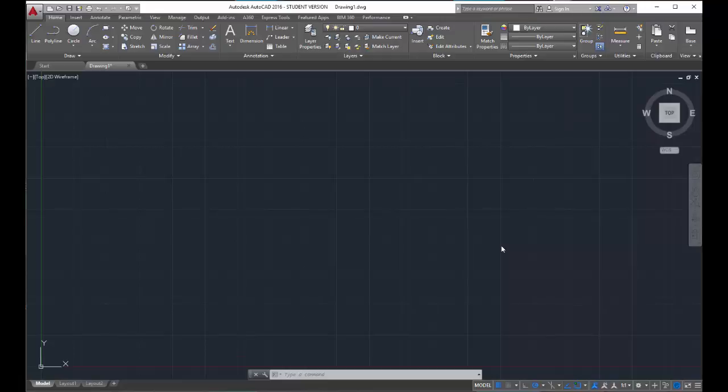When we draft with AutoCAD, oftentimes we draft objects comprising multiple shapes, like doors, furniture, that kind of thing. They all have more than one line. Well, it makes sense then that when we're dealing with these kinds of objects, we should bind them all together to make them easier to move, rotate, and modify. So, AutoCAD allows us to turn multiple shapes into blocks, basically super gluing them together.